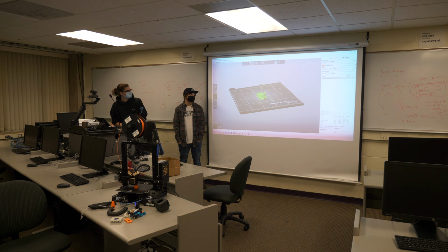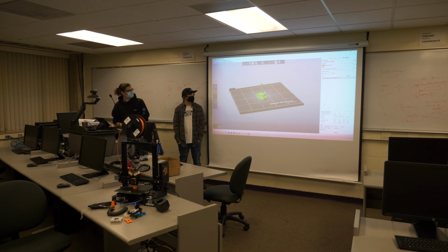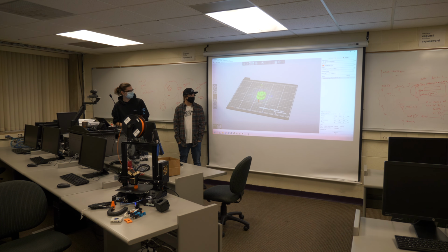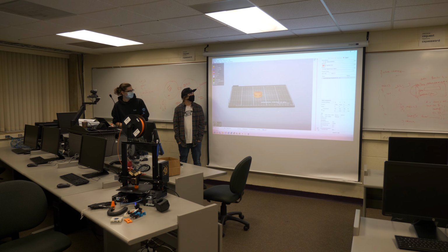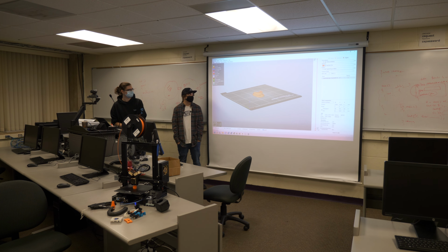So this is an example of one slicer. There is also this, which is Elegoo's Cura. So you can just see this is going to be the general layout when you bring something in. You are going to be placing your object down and manipulating it in here. After this, you generate code. This is what tells the 3D printer what to actually do. And you can actually go through and examine the individual layers of the piece as it is going to be built by the 3D printer.